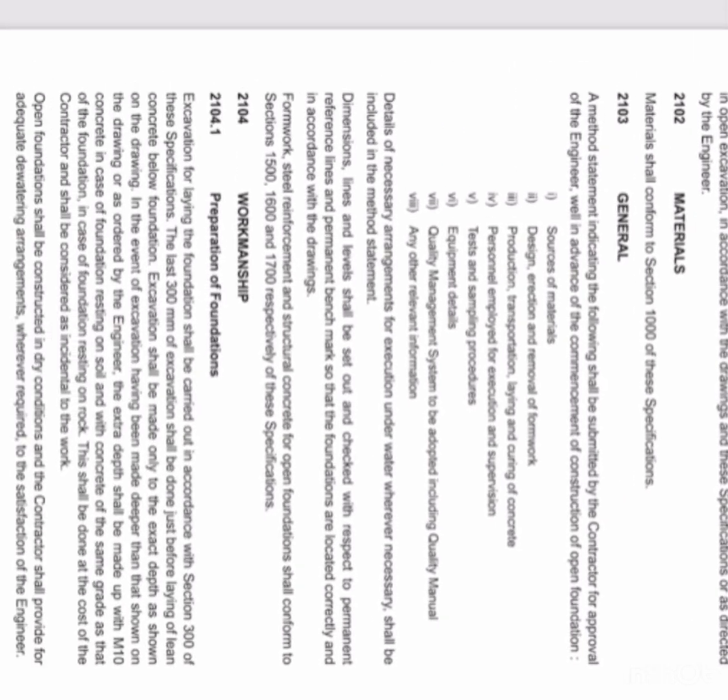Dimension, lines and levels shall be set out and checked with respect to permanent reference line and permanent benchmarks so that the foundations are located correctly and in accordance with the drawing. Formwork, steel reinforcement and structural concrete for open foundations shall conform to section 1500, 1600 and 1700 respectively of these specifications.